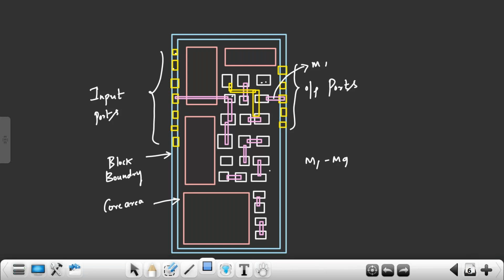So what is critical path? You will understand only when we understand what is STA, static timing analysis. For example, this routing is coming under the time critical path. Means I am seeing this cell is coming under time critical path, means in this path I am seeing timing violation. Now route with higher metal layer because higher metal layer has less resistance and they have less delay, right? So based on that, my tool will decide which metal layer I have to use out of M1 to M9.